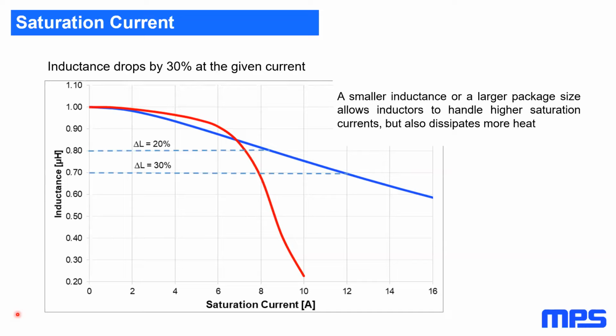All right, and sorry, Sven, I didn't make a note of when this one came in, but magnetic shielded is related to emissions? What's the question? Yes, so when we have this kind of magnetic shielding, like in the semi-shielded inductors, it's not going to be 100% shielded. The strongest shielded inductors are the shielding ring type and the molded type. Then there are the non-shielded inductors, and the semi-shielded will be something in between in emission. So it's magnetically shielded, but it's not 100% like a shielding ring inductor.